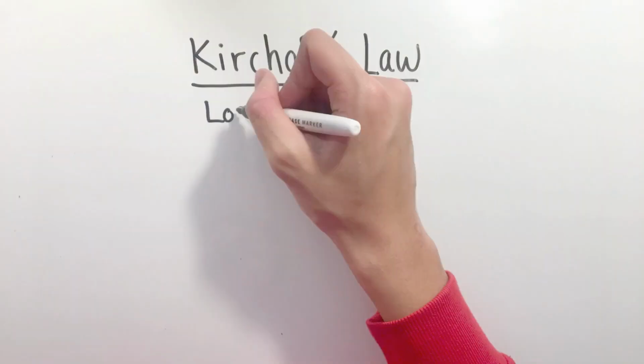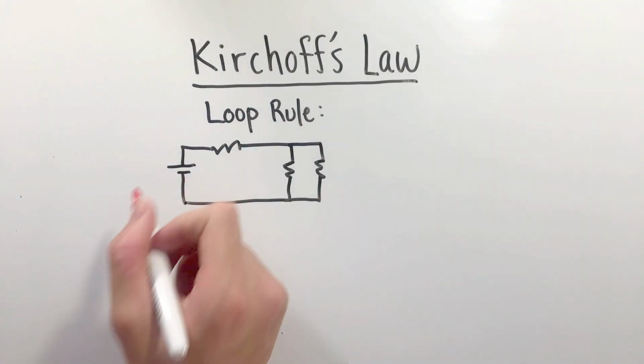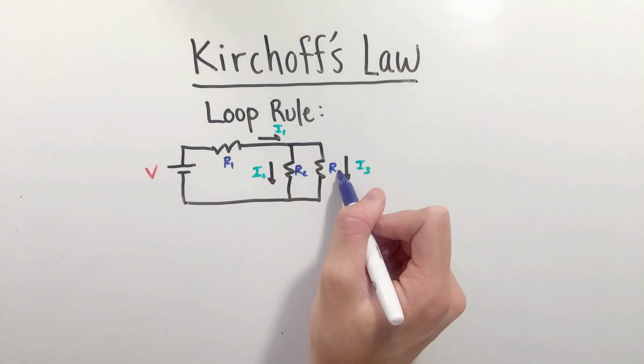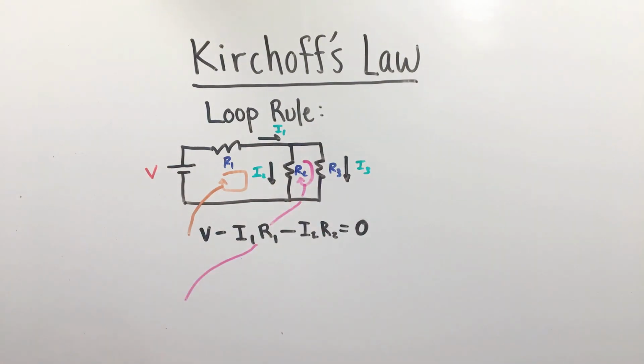The other part of Kirchoff's laws is Kirchoff's loop rule, or that the voltage drop across any closed loop of wire within a circuit must always equal 0. To express this idea mathematically, we take our circuit loop of choice and work our way around. Crossing batteries from short side to long side is a positive voltage jump equal to the battery's voltage, while long to short is a negative voltage. For resistors, tracing across a resistor in the direction of the current is a negative voltage drop given by Ohm's law, while loop directions opposite to the current are positive potential differences.